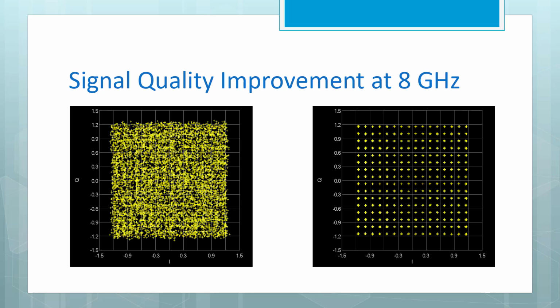And so we used a fixed calibration. You can use any waveform you want. I like chirps. I used a chirp and determined the FIR tap coefficients, and then we applied that to the 256 QAM signal and saw that we were able to get a good signal, and then we used adaptive equalization to just kind of clean things up, and we get a nice response. So basically we go from something with no information being conveyed, like on the left-hand side, that symbol constellation, to something on the right, which is really very good, despite the fact that there's a lot of imperfection in the